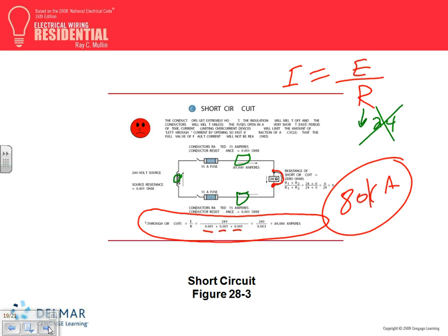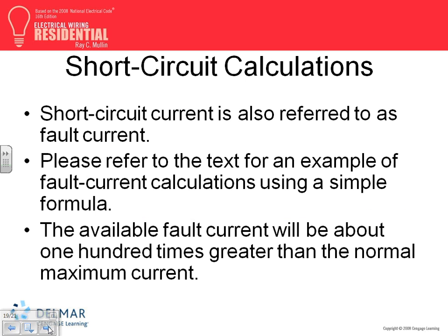Why? Because look at the conductor impedance. If the conductors are too long, that impedance becomes high, then it lowers the short circuit current. If I put equipment right next to the panel, the short circuit current is going to be very high. So there's advantage and disadvantage of having the loads right close to the panel that feeds them.